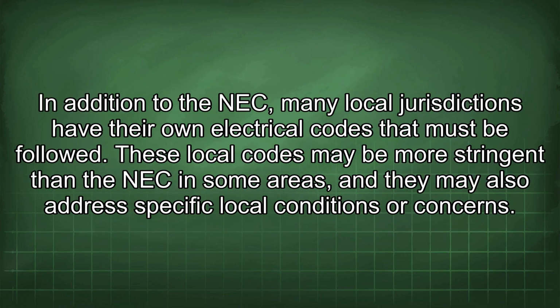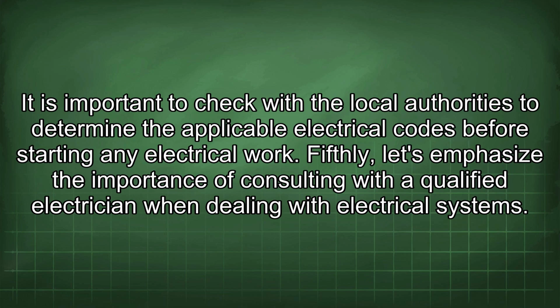In addition to the NEC, many local jurisdictions have their own electrical codes that must be followed. These local codes may be more stringent than the NEC in some areas, and they may also address specific local conditions or concerns. It is important to check with the local authorities to determine the applicable electrical codes before starting any electrical work.